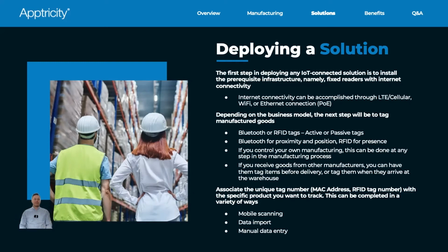So Bluetooth is more done in a circular manner. It basically creates a radius around the antenna, and then the tag itself creates a radius where it pings out its signal. But you have options, is essentially what I'm getting at, when you're associating or connecting antennas to the controller, and then you can run long cable and put them pretty far distances away from the controller itself.